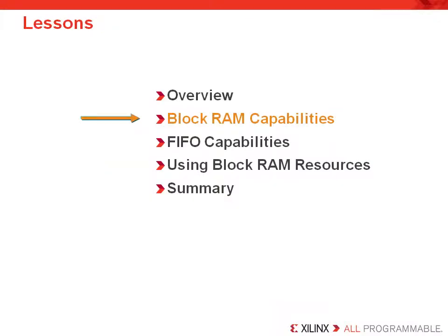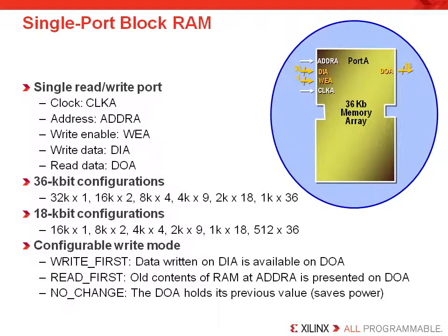Now let's take a moment and look in a little more detail at the block RAM capabilities. As I mentioned, these block memories are true dual-port memories, even though in this slide we're just looking at a single-port configuration. This means you have a ton of flexibility, but you also need to make sure that you're driving the ports properly to avoid any problems. Now the ports available to you for single port configurations are listed here on this slide.